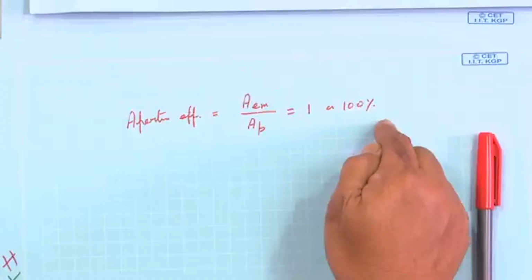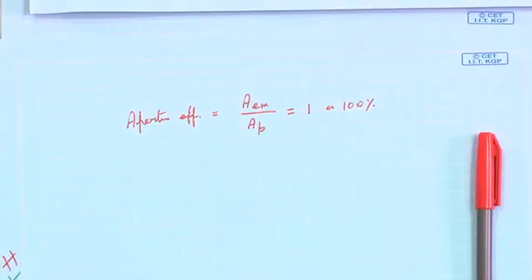If I do not illuminate the aperture uniformly, I won't get this. While introducing array antennas, in the first lecture I said that we try to make the antenna large in terms of lambda. So, some factor of that physical area will be the directivity.